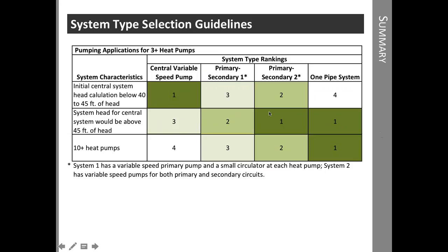All right, so when we get into the 3+ systems, it becomes really a function of system pressure drop. The very efficient ECM circulators like the Magna 3 that I had in the picture earlier with the NP multi have a limitation, and that limitation is about 50 foot of head. In differential pressure mode, it may be closer to 45 foot, depending upon which pump we select. So that's our first thing to look at.